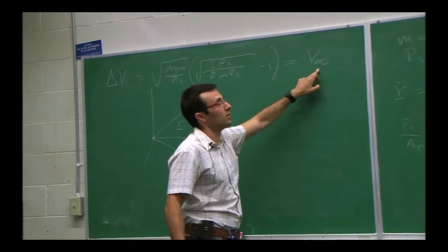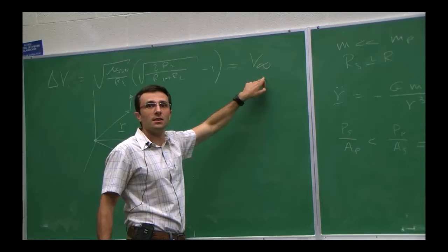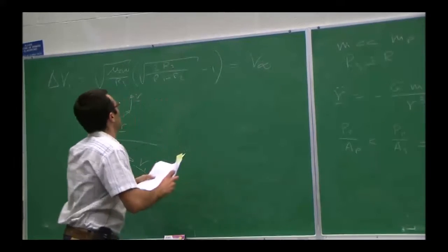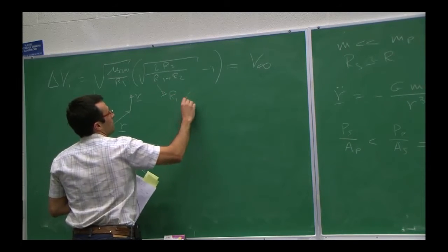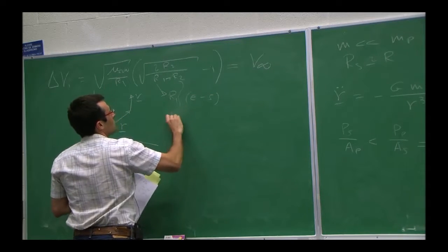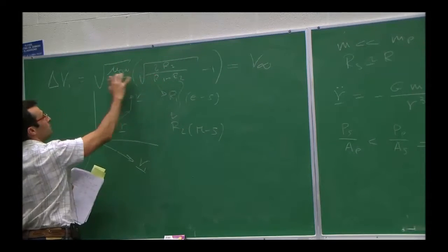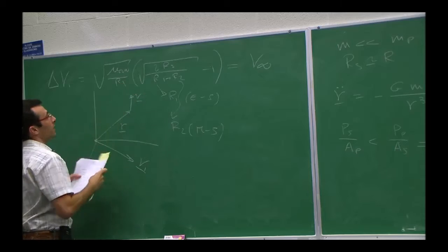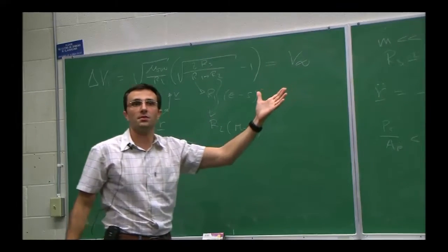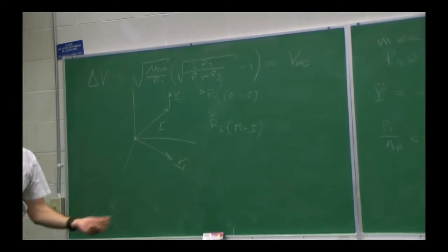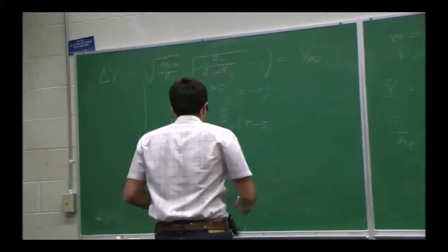Here it is. You need to make sure that you're leaving the planet on a hyperbolic path that has exactly this V infinity. This is a number. If you go into Mars, this is the radius of the Earth around the sun, right? R1, this is Earth, Sun, and R2 is Mars, Sun. So everything here is known. Mu of the sun is a constant. You want to go there on a Hohmann transfer, this is how much speed you need to have above the velocity of the Earth, on top of that. Okay? So how do you make sure of that? So the V infinity is basically a given, okay?